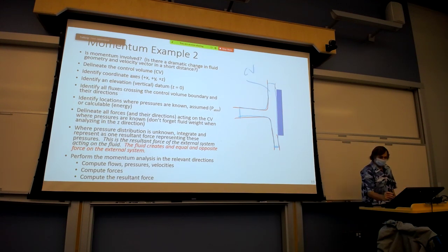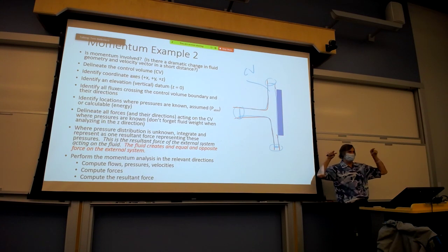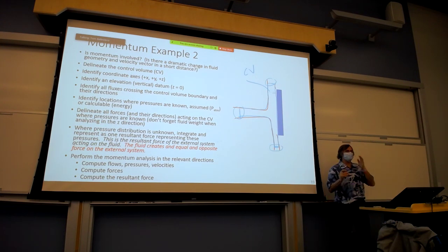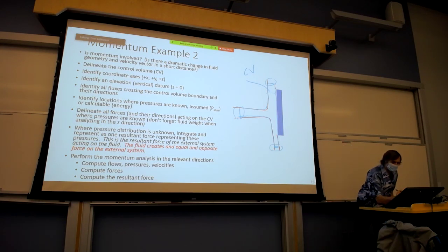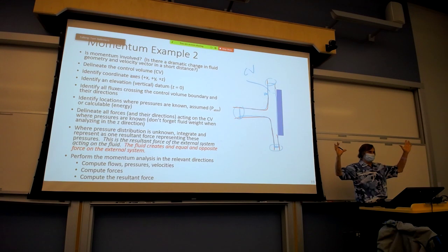It's all the fluid, and we went out here for a few reasons. One, at all those locations, again, it's one-dimensional flow. But two, those are free jets. If you had gone back somewhere onto the plate, it's not a free jet now. There's a pressure distribution at the bottom of that fluid, and it permeates to the top of the fluid, where yes, up here at the top of the fluid, you have atmospheric pressure, but not throughout the rest of the water flowing against the surface. So you extend the control volume to beyond the plate.